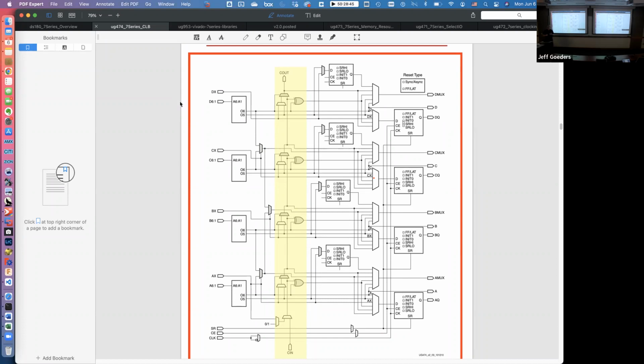Yeah, that's called a ripple carry adder, and that's a fine adder. But they learned early on when they started making FPGAs that for many designs, the limiting factor to how fast the circuit would run is all of these carry chains in adders. That tended to be a critical path. Well, if you go take a computer arithmetic class, we used to teach one. There's been lots of ways to speed up adders. And they don't look like what you saw. What we did in class in 220 was called ripple carry. But there's things called carry propagate generate and carry look ahead and carry select. Okay, there's been a lot of ways of doing it.